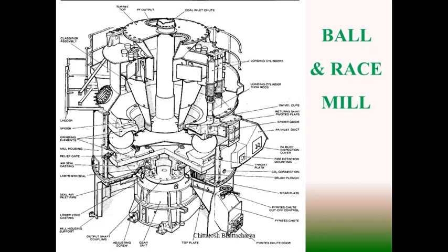The lower ring is fixed with the mill yoke, and this yoke is connected to the vertical shaft, so the bottom race is rotating, and above that hollow grinding balls are placed, and these hollow grinding balls are loaded from the upper ring, which is again loaded through pneumatic loading cylinders from an external arrangement.